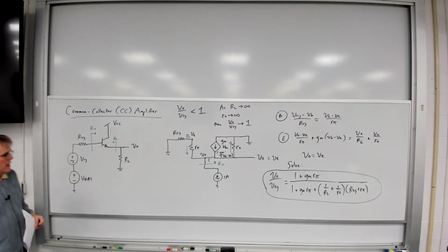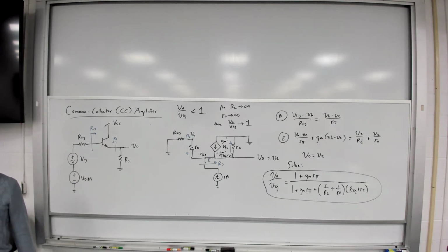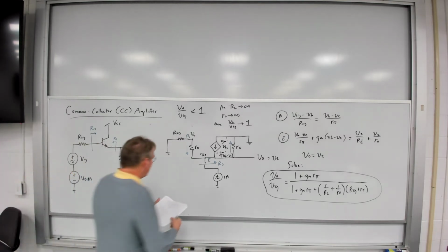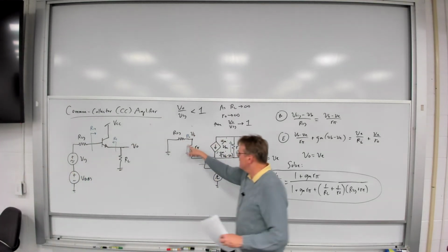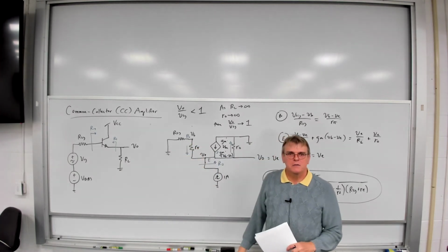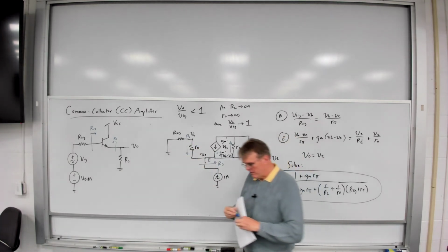And again, haven't we seen this? Yeah, we did this for the common base circuit, for the input resistance for the common base, which also happened to be just like the little R sub E calculation, all right? Except it's a little more complex now because we've got this additional resistance here, the R sig. So the resistance terms are a bit different.